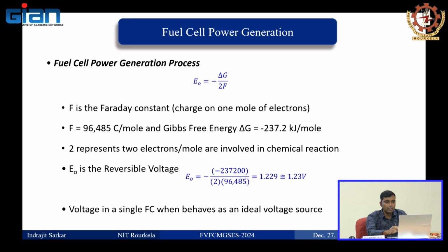So these are the equations. Okay, from here, the thing we need to look into is that it is generating a voltage of 1.23 volt, which is not sufficient. Even that is under open circuit condition. When you are loading anything, the voltage comes down. You must know this, because there will be some internal impedance, and when you increase current, definitely there will be a drop and decay in the voltage as well.